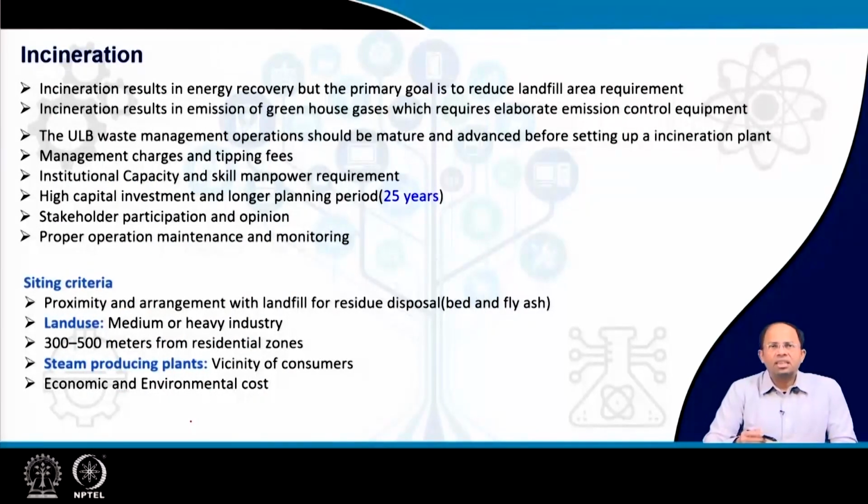So incineration results in energy recovery, but as you understand, along with energy, it results in a lot of emissions. So we have to be very careful, and the entire process is also very, very costly. So the primary goal is to reduce landfill area requirement. So usually we will take up incineration or similar process when the land area is very, very costly and there is no suitable area available for landfill sites and all. So that is when we will consider incineration.